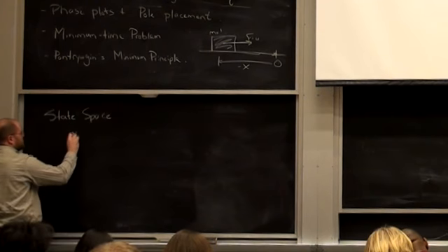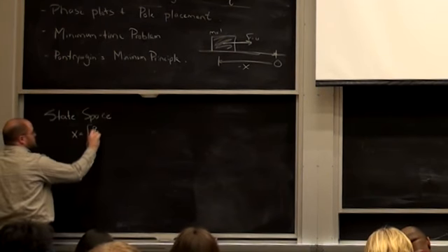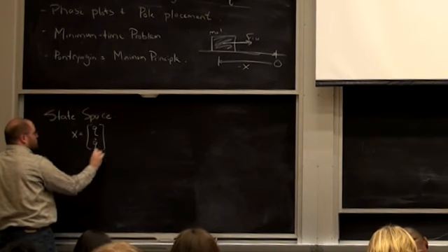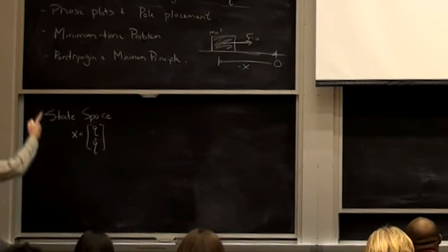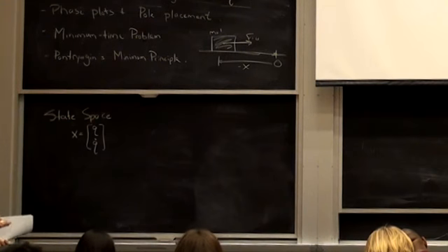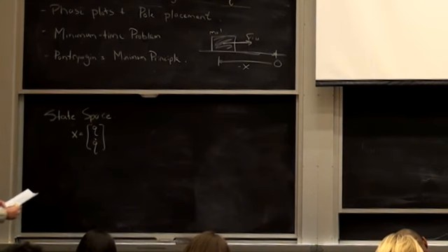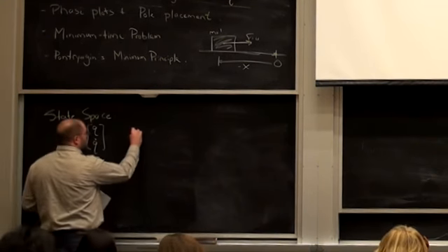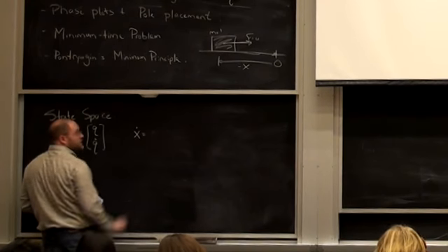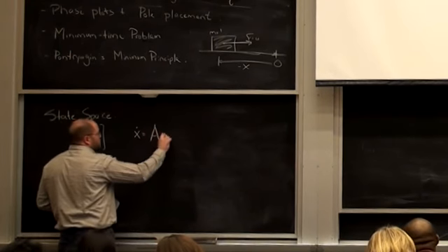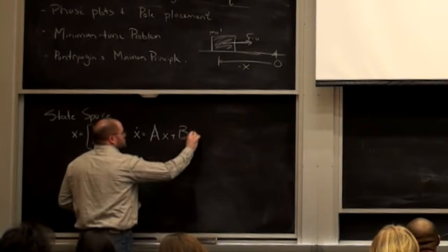It's going to use the vector x to be, in this case, q and q dot. Okay? And that dynamics there is the simplest state space form you're going to see, but a state space linear equation will have the form x dot equals Ax plus Bu.